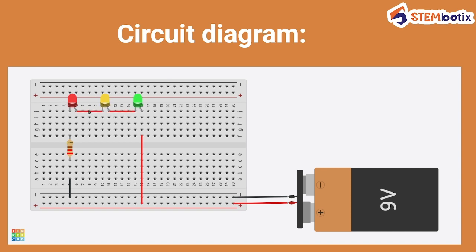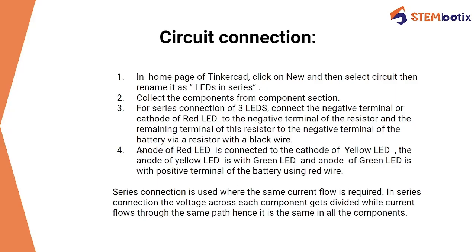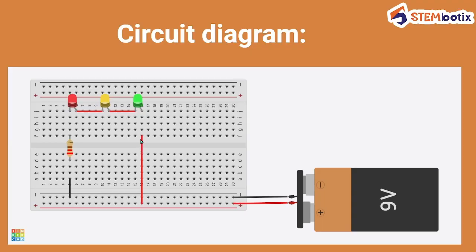These are the three circuit elements which are connected in series, and you can see that because all the devices share only one common node. They share this common node. Also, let's say this is the starting point. Starting from here, going here,